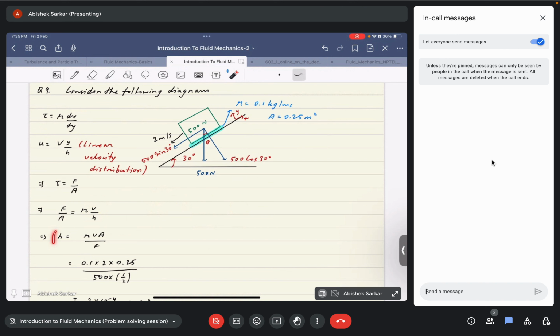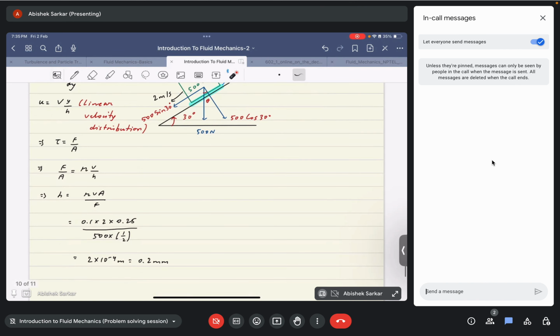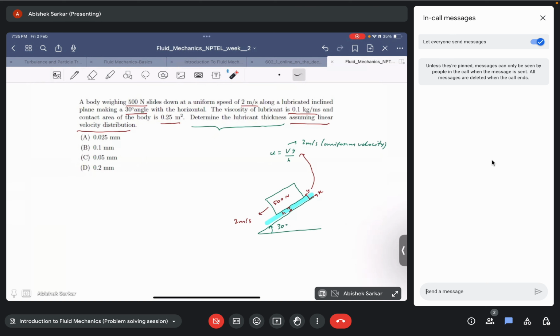Then again just mathematically manipulate it, because h is the quantity that we need, so h would be equal to mu V A by F. Just substitute the known values here to get that h is equal to 2 into 10 to the power minus 4 meter, or 0.2 millimeter. So the correct answer would be option D.